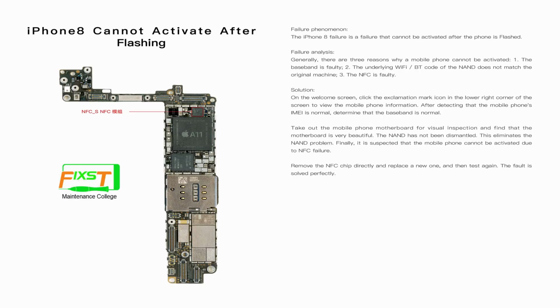Okay, this is the next case. The iPhone 8 cannot be activated after flashing. Generally, there are 3 reasons why a mobile phone cannot be activated. The first is that the baseband has failed, the second is that the Wi-Fi and BT data of the NAND is not matched, and the third is that the NFC has some problem.